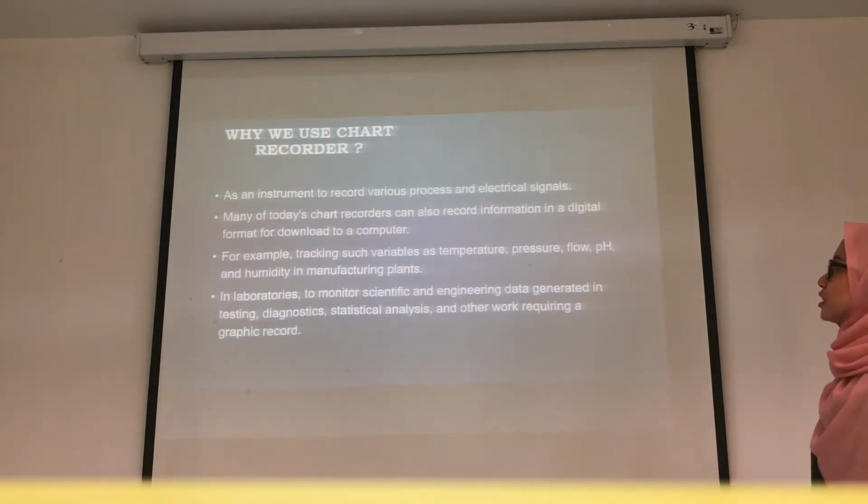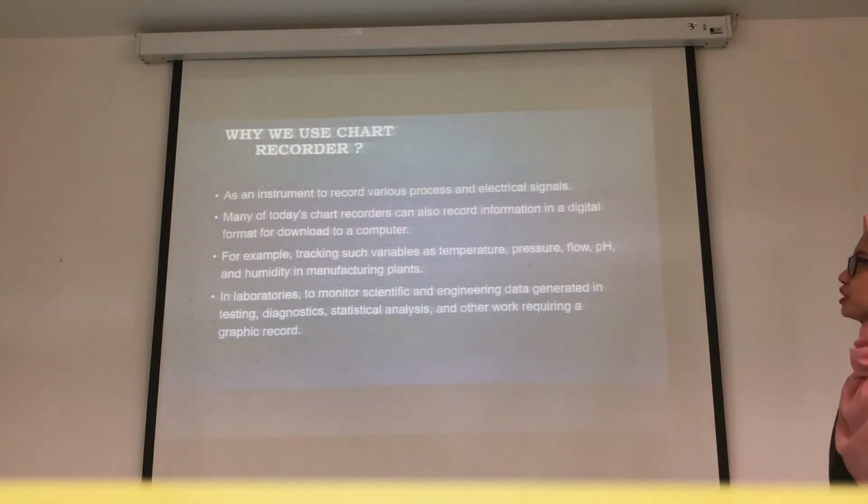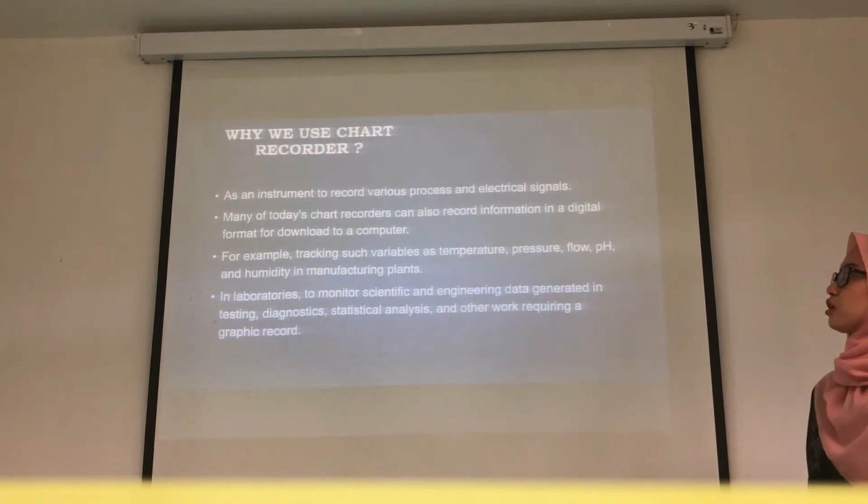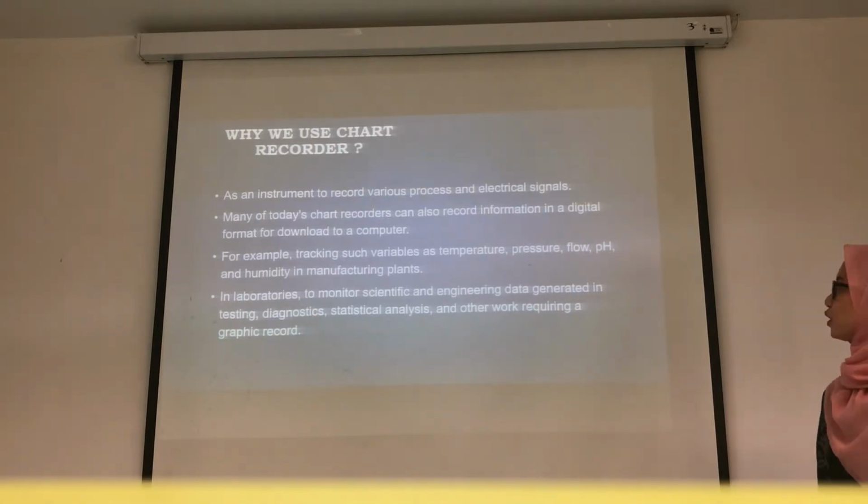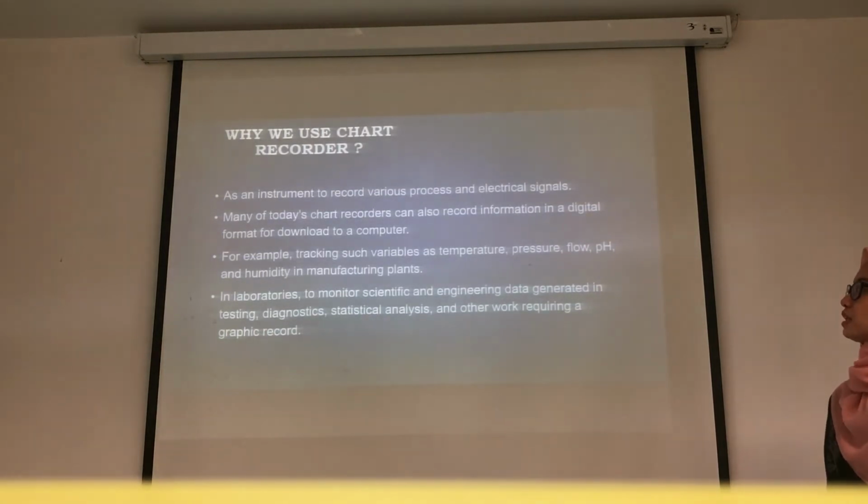I will explain why we use the chart recorder. First of all, we use the chart recorder as an instrument to record various process and electrical signals. Then many of today's chart recorders can also record information in a digital format for download to a computer. For example, we use it to track variables such as temperature, pressure, flow, pH and humidity in manufacturing plants. In laboratories, we use it to monitor scientific and engineering data generated in testing, diagnostic, statistical analysis and other work requiring a graphic record. And I will pass to Shahinda.